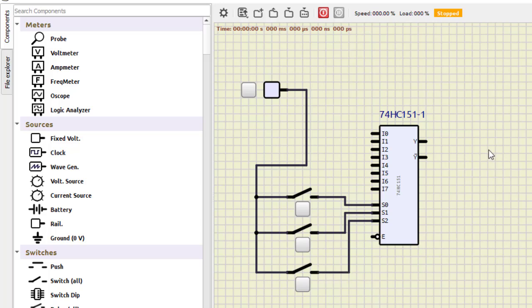Now for our function we need 0 2 5 7, so you can check the text. So I will just connect this 7 directly, I just turn it on and keep this 7, then 5, then 2, then 0. Now the remaining lines, which are not there in the function, we need to connect to ground, so I just select this ground here and connect it with all the remaining lines.